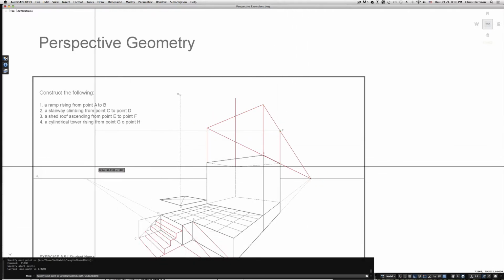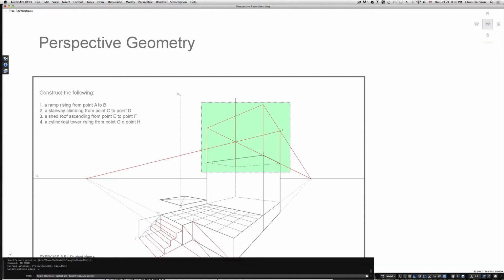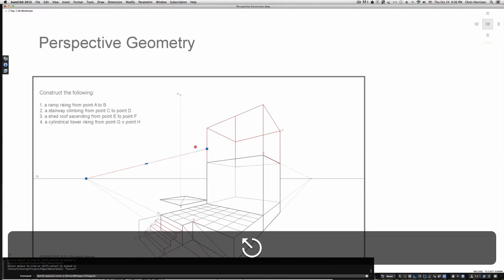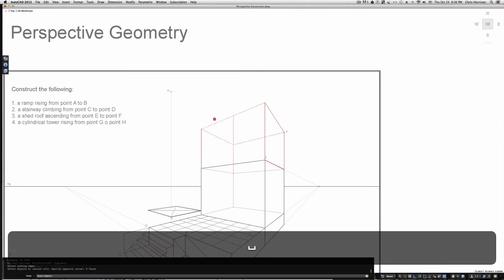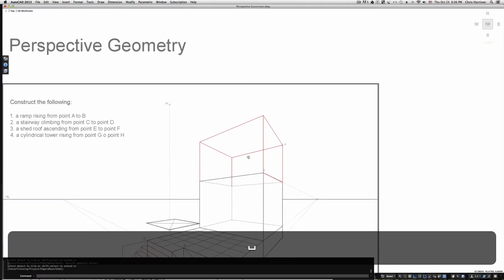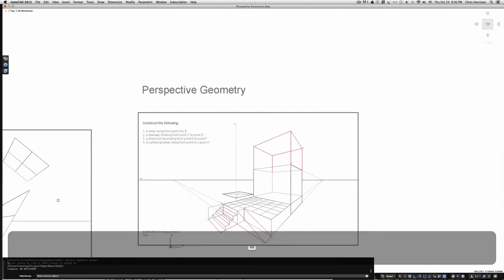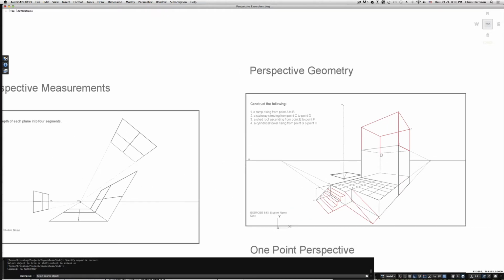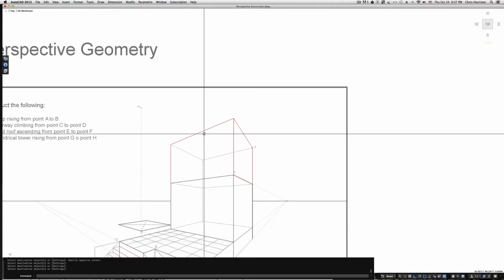Now in this back corner, I'm going to bring this back here to this vanishing point as well, and then likewise to the other side. Then I'll clean this up. It's right there, there. Okay, so there goes our box. Guess I should trim that as well. There we go. So now what I'll do is just match some properties, because that's going to be a dash line in the background anyway. So let's just use this. So we'll have that, that, and that we won't see. Okay, great. So there goes the box, the extension.